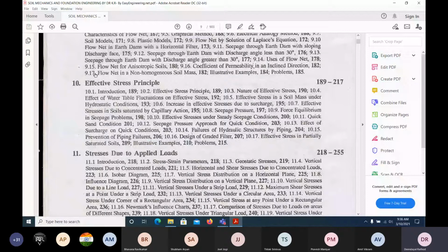So whatever we have seen here in the effective stress, that is the load due to the self weight of a soil. Hope you are following, right? That is at a ground without any weight. Self weight is there. How can we find out the effective stress at a particular depth? Gamma into h. h is the height, gamma is the unit weight of the soil. That soil unit weight can vary, okay, it can be gamma dash, gamma w. If it's only water, or gamma dash, that is submerged, or gamma dry, and so on. It depends on the soil.